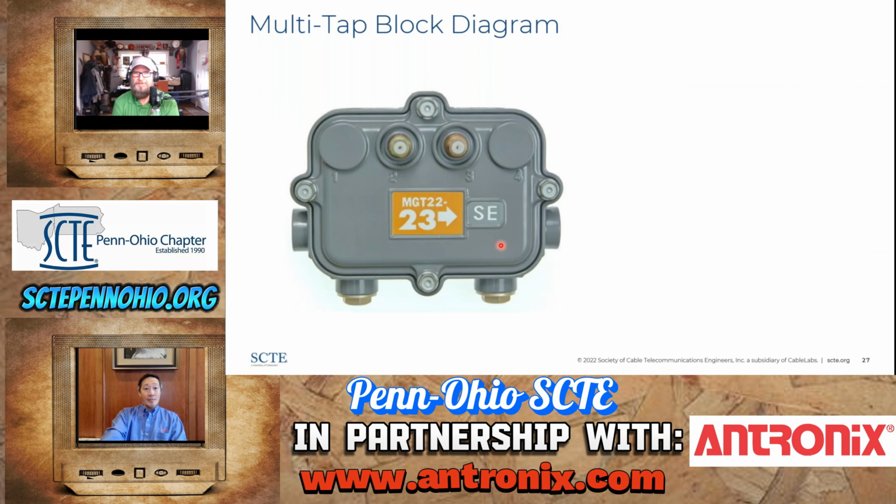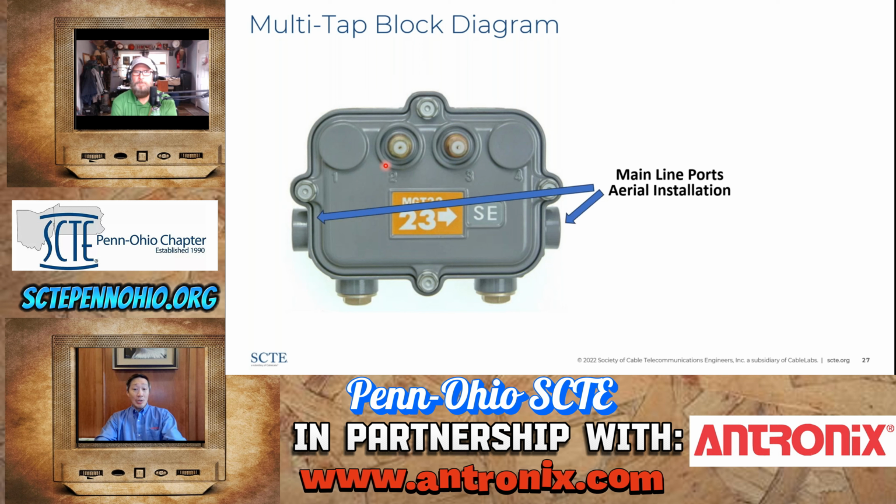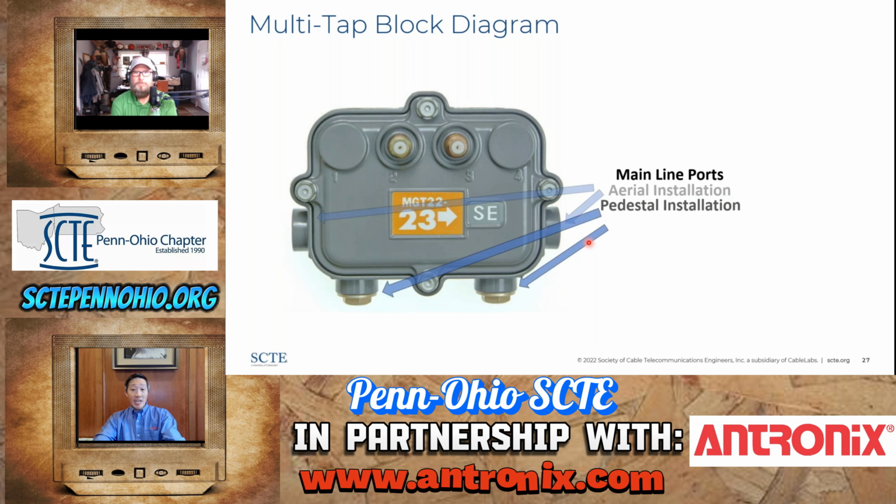All right, thanks, Neil. We're going to go through a block diagram of a tap. So first, what are the main components of a tap? These are the tap ports, F ports, that go down to the drop. Taps can be installed from the input port on the left to the output port, in aerial installation, so your hardline connectors go in from the left and the right. You can also install a tap in pedestal installation, where the hardline comes in through the bottom and out through the bottom in a pedestal.